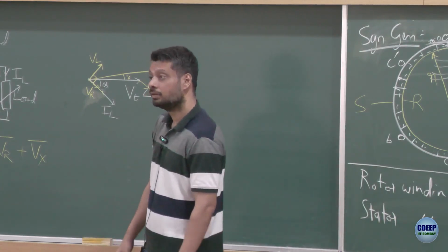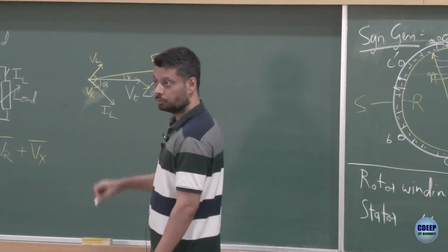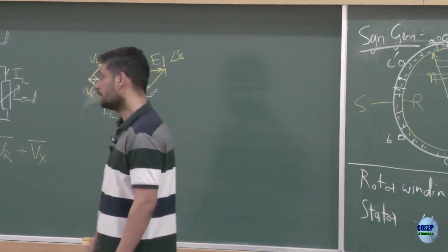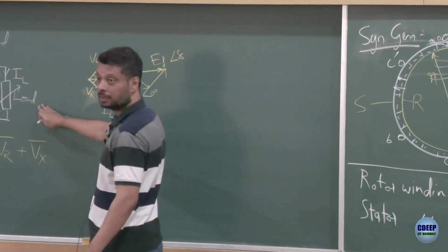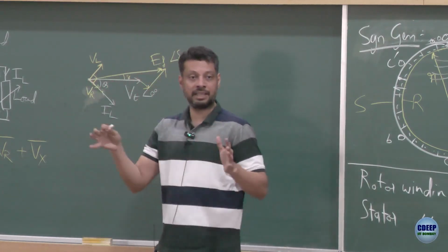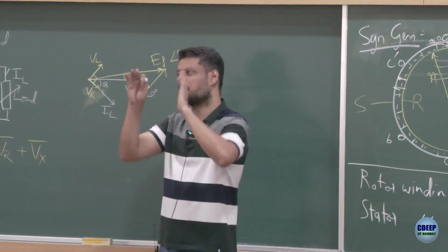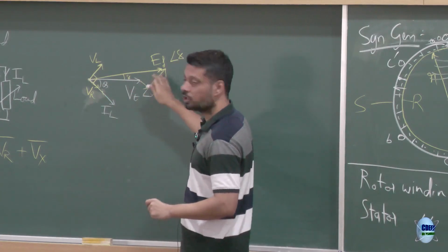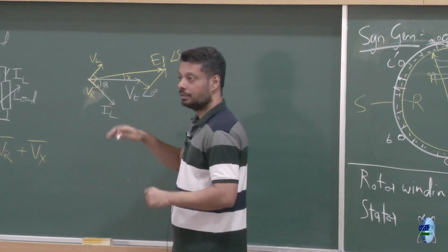Of delta you mean or theta you mean? What angle? Delta, yeah. So if load is variable, that means both load magnitude and load power factor can vary depending on what you turn on and off. Then these two, the yellow vectors, would also be variables which are getting added.